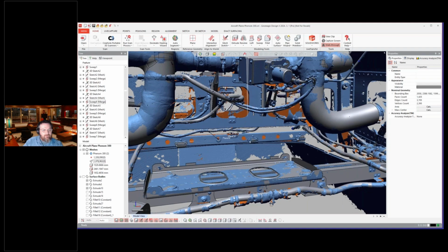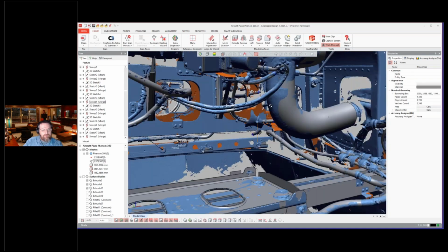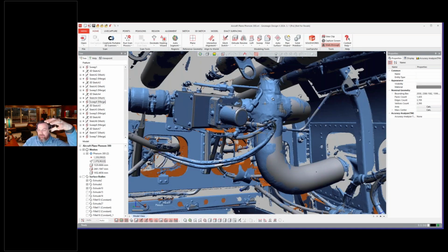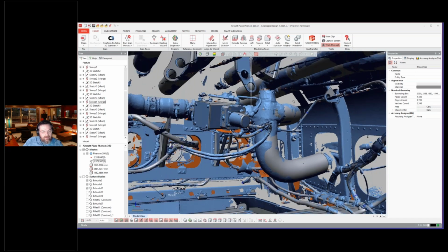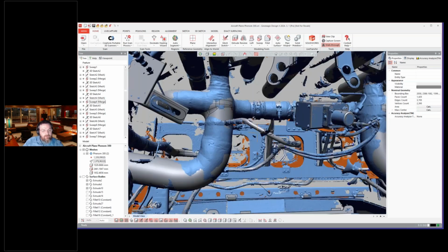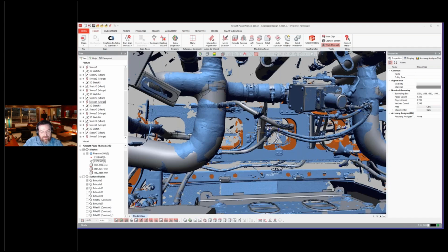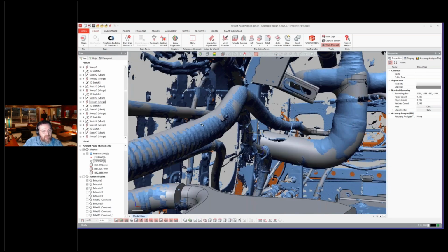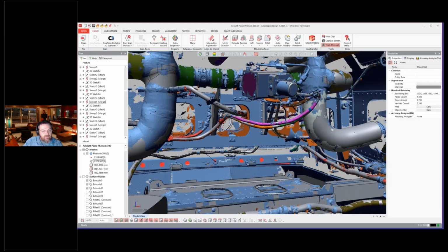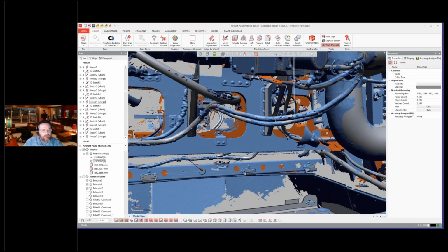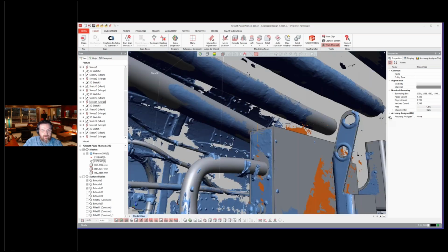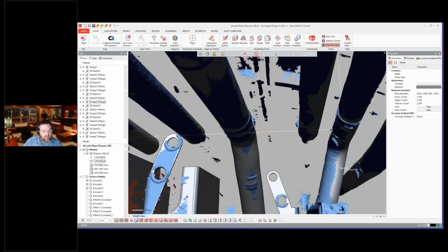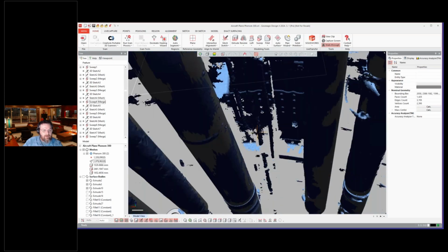But walkthrough mode is, instead of rotating the object on screen where you're outside and the object's sitting here and you're rotating around, walkthrough is rotating your camera around and moving it. So the best way to do this, and what I'm doing now, once you go into walkthrough mode, is scroll on your mouse wheel to walk forward, up, down, wherever, as you walk through here to look at everything that was modeled.